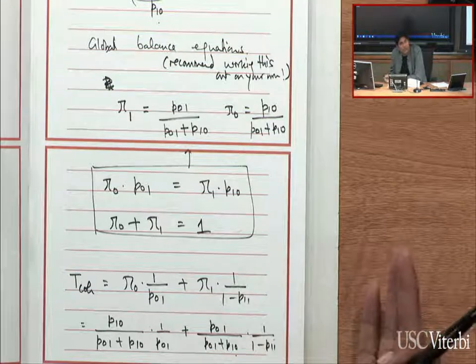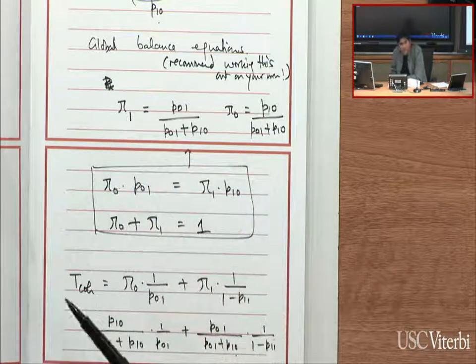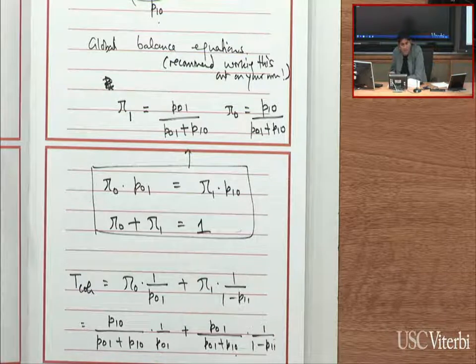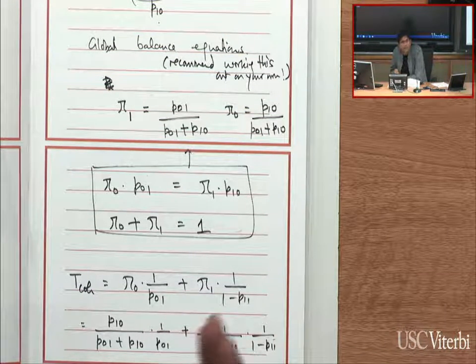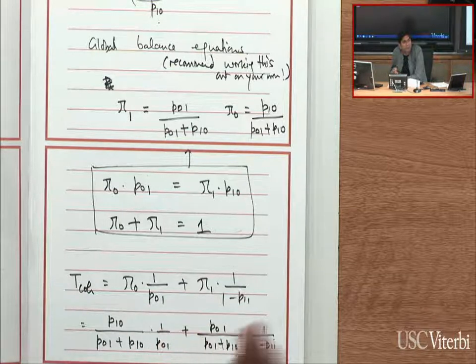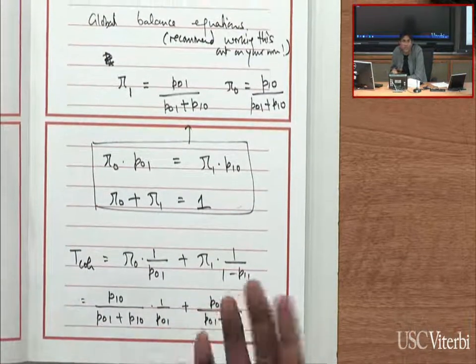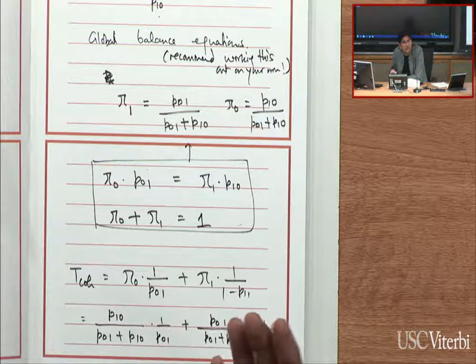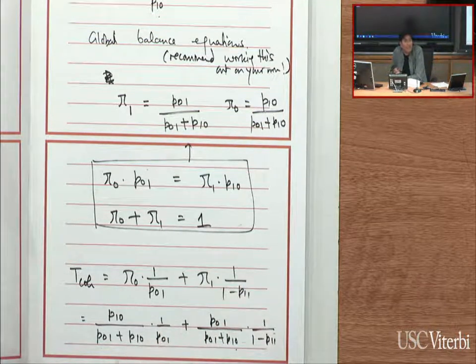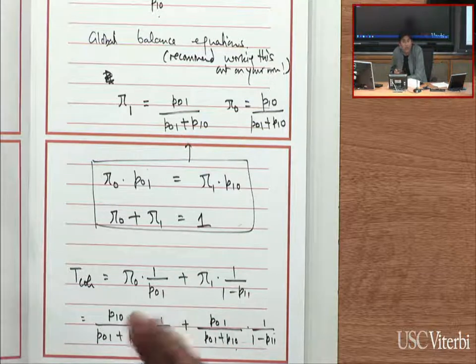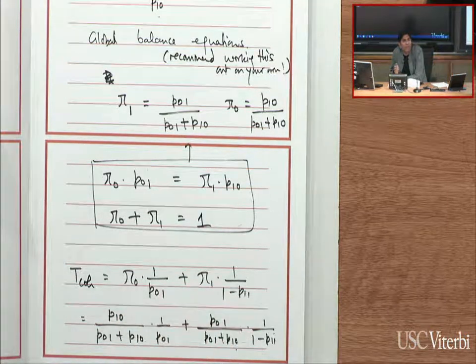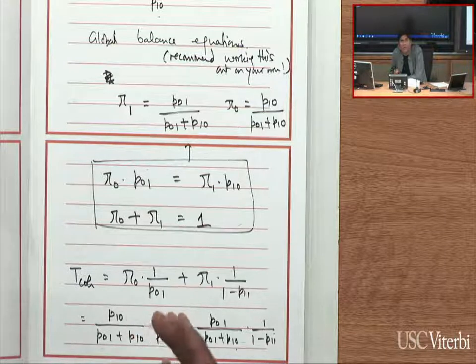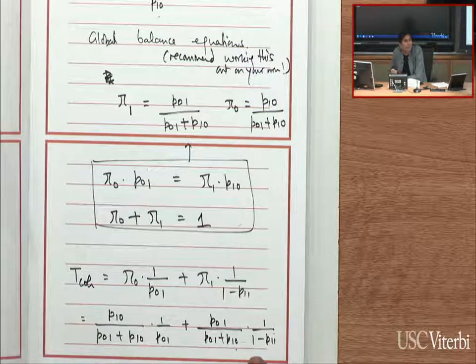And in one of the assignments, we'll see, using such a model, given this coherence time parameter, what's the best time to retransmit a message? So if I've just sent, I think we talked about it last time, if you send a packet and you didn't get back a response because the packet didn't go through, then that means that you're in a bad state. If you've learned the model over time, you've learned that the channel tends to stay bad for this period of time, then that might inform how long you should wait before resending the packet again.